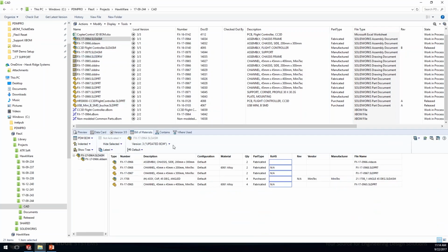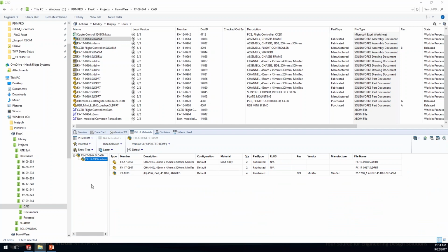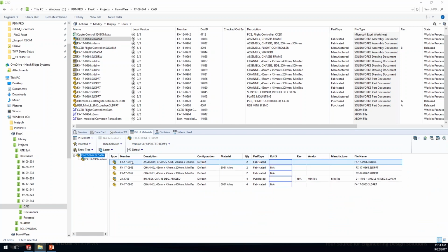So if we look at the PDM bill of materials, in the structure here, if we show the tree, we're seeing that subassembly. I don't really want to see that subassembly. We see it here, and it says it's got a quantity of 2, and then there are these over here as well. Likewise, these end caps. Now you notice these don't have a way to expand them, so these are getting honored. It understands the hide feature, but so far it doesn't understand the promote feature.